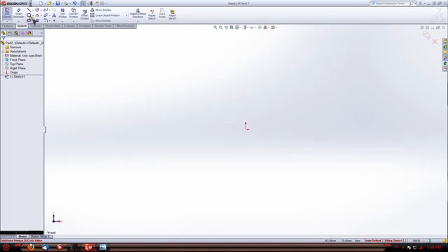So your basic drawing commands are line, rectangle, slot, circle, arc, polygon, spline, ellipse, and fillet. There's also text and point, and those are useful. Text is obviously useful if you want to emboss your model with text or symbols or something. Points are really only useful for a very complex kind of modeling called lofting, which won't be explained in this tutorial, but maybe later on down the road I'll make a lofting tutorial.